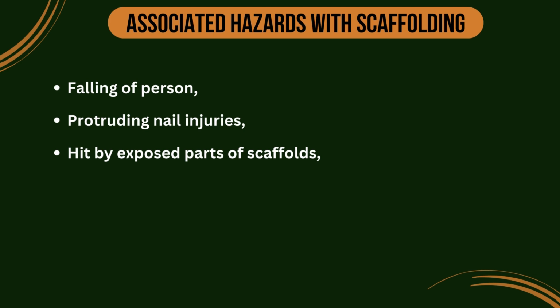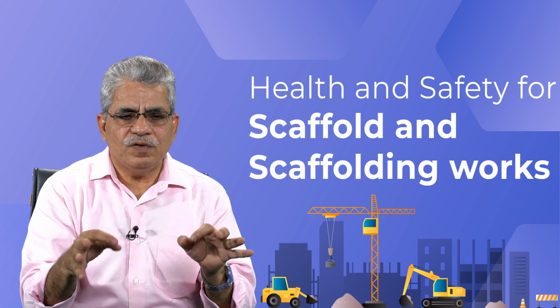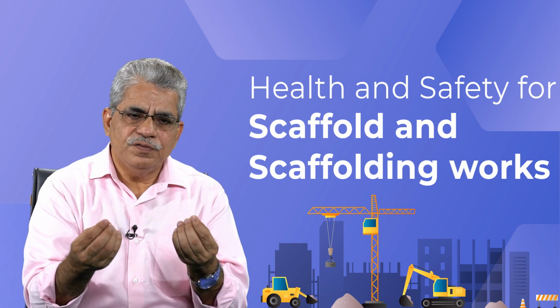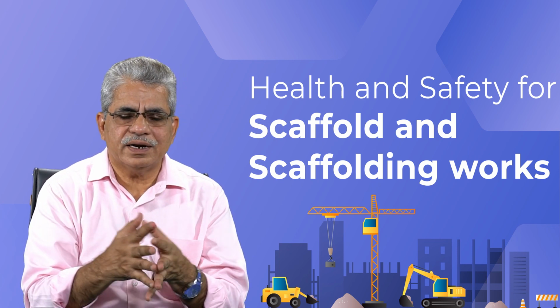Then there may be overhead electrical lines, which are live wires basically, and if some person or the scaffold comes in contact with these overhead electrical lines, there may be electrocution of the workers, which may be very deadly. So we have to be careful that while erecting or using the scaffold, we take care of the overhead electrical lines.